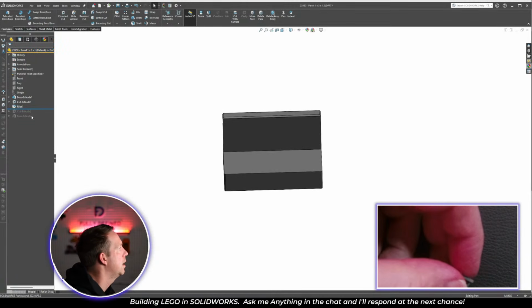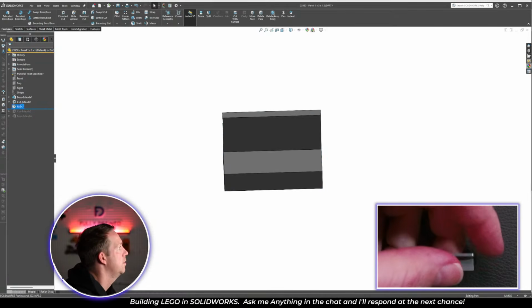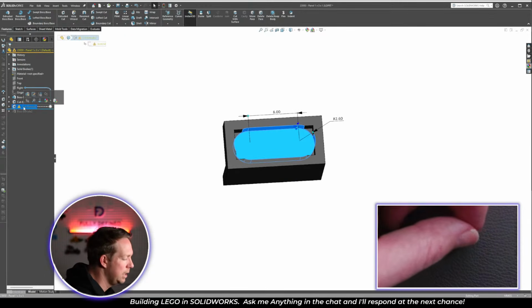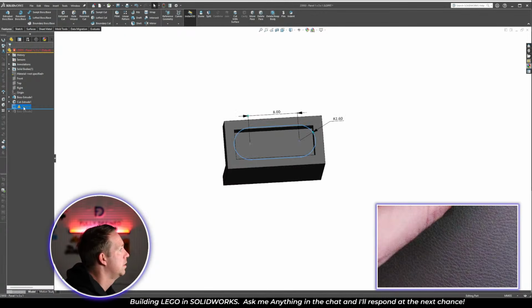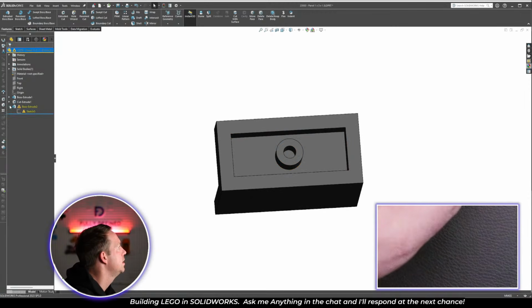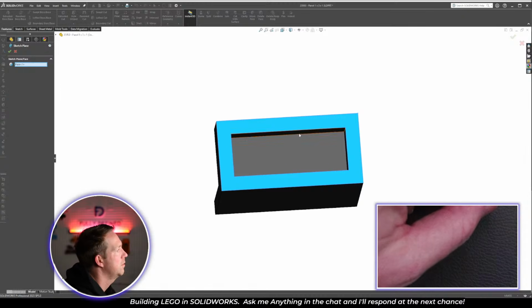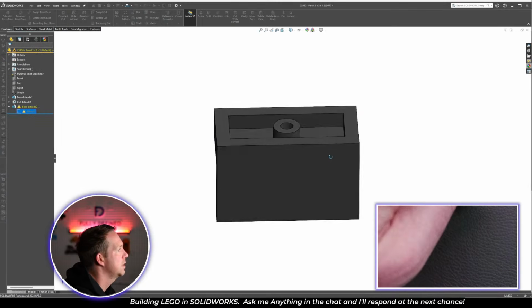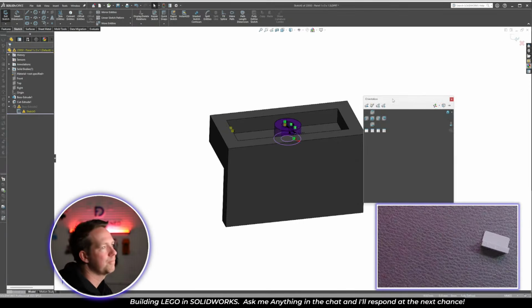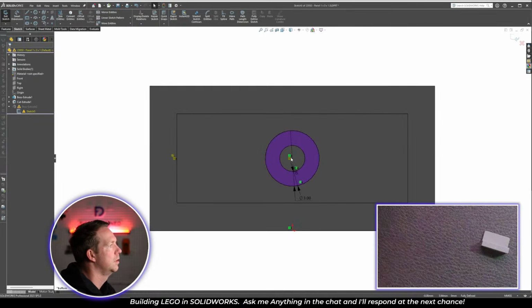Looking good. I'm not going to keep those fillets, get rid of those. Cut extrude here, I'm going to delete, don't need that. And then I'll just keep the last feature on the bottom. And that makes it nice and easy. Just make sure I've got all the sketches. Update the dangling dimensions. Simply a midpoint to horizontal relationship here.